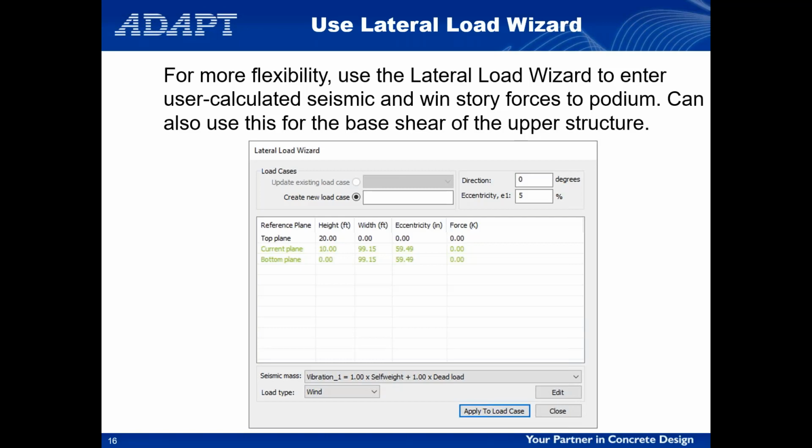There's one question that was just asked that said, how would you apply the wind load to the upper wood structure? That's a good question. I'm assuming that the loads that we're applying, remember we started out the session by saying you have those lateral loads that are defined as couples. The default scenario is that you have a set of couples for your seismic and for your wind.